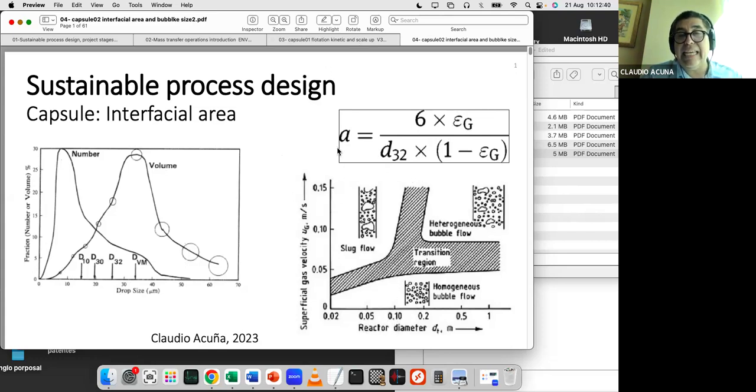And again, this idea of interfacial area is to improve the kinetic process. Let's say if you have a kinetic leaching process with 400 microns, you need to understand what happened with the kinetics. You need to understand the fundamentals when you reduce size from 400 to 200. Or if you change the volumetric content of solid, you will see an effect in kinetics. And again, you need to understand the fundamentals. Okay, that is the chapter, module 4.